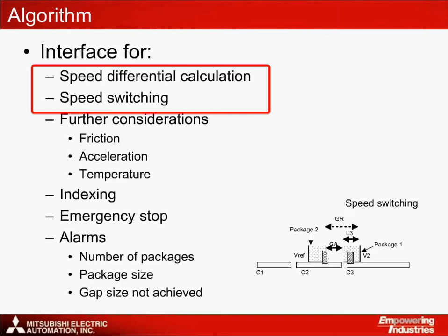The timeliness of when to switch the speeds is also very important. This is carried out using the application's optical sensor to determine where the package is on the conveyor and then to determine when to change the speed of the conveyor.